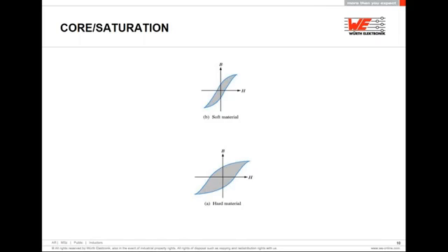The coercivity is the resistance of a magnetic material to changes in magnetization, equivalent to the field intensity necessary to demagnetize the fully magnetized material. Soft magnetic materials are mainly used in inductive components, whereas hard magnetic materials are mainly used as permanent magnets and with electromagnets.